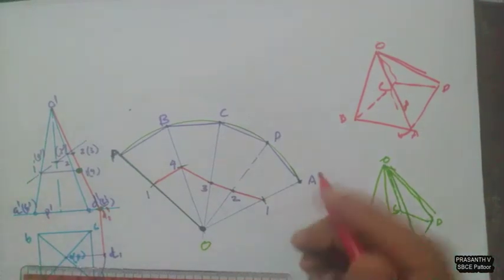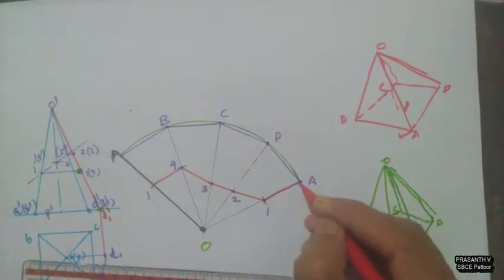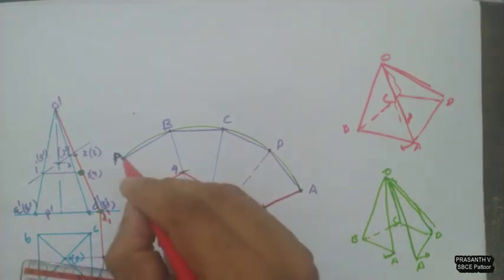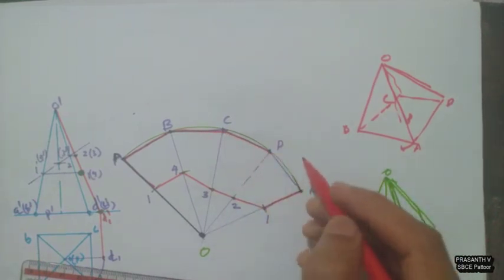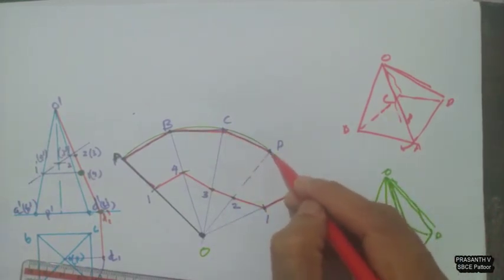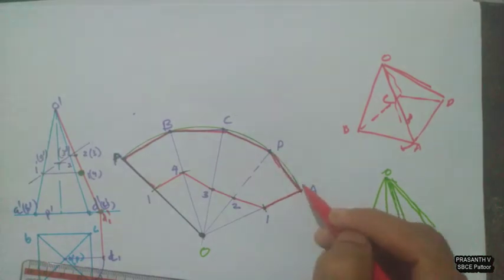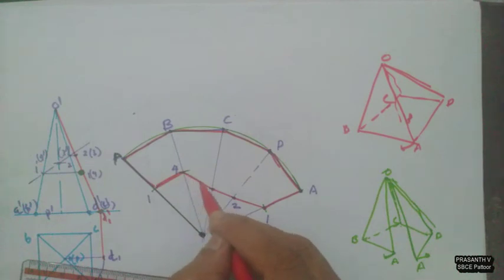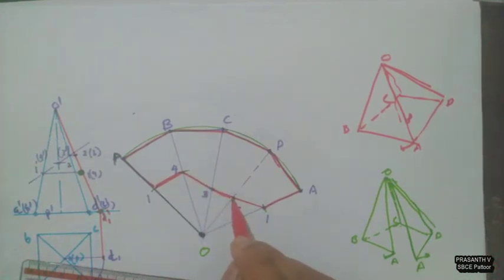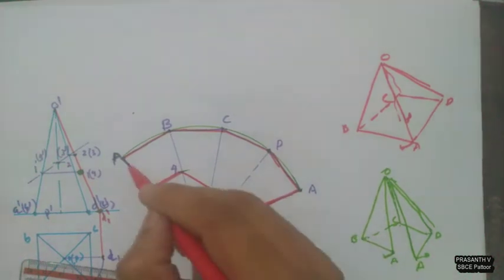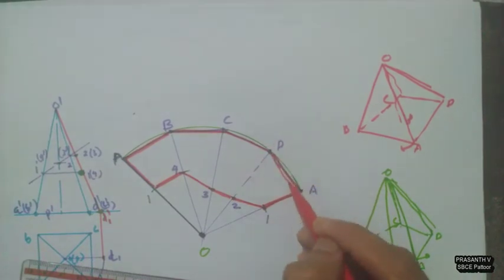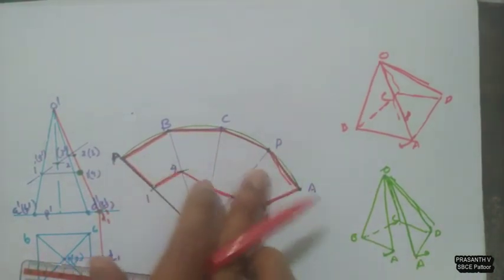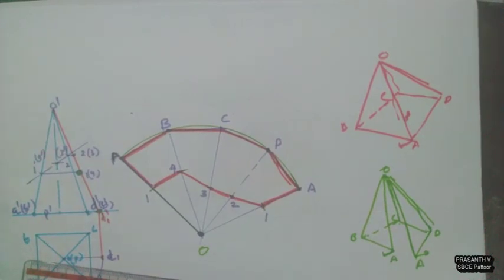You see, this will be the bottom portion of the pyramid. I am just outlining the bottom portion. Keep one thing in mind, that all the boundaries of the portion should be thick lines. All other lines should be thin lines, so you have to keep this properly. So this is the bottom portion of the pyramid. That's how we do a particular problem on a square pyramid.